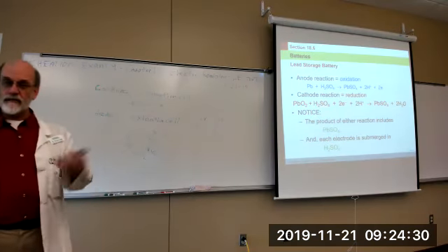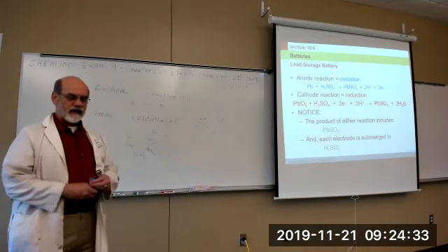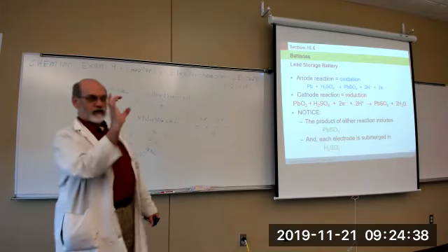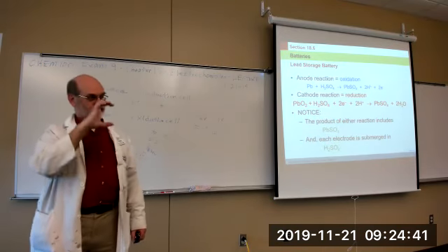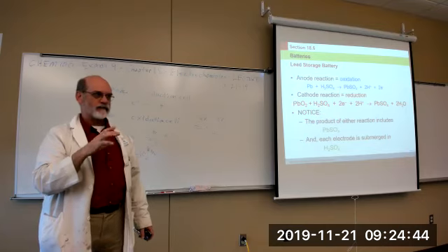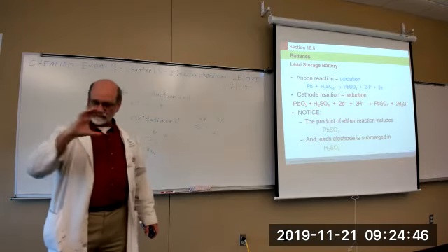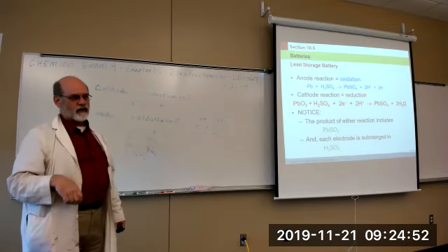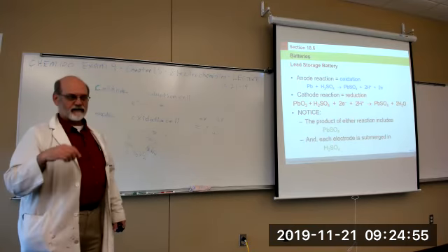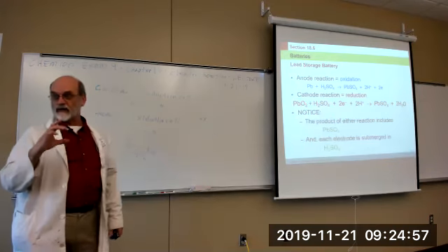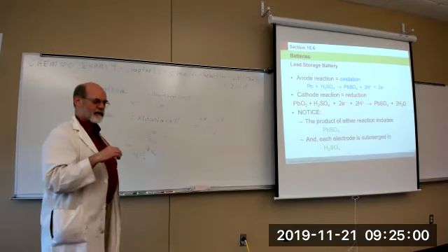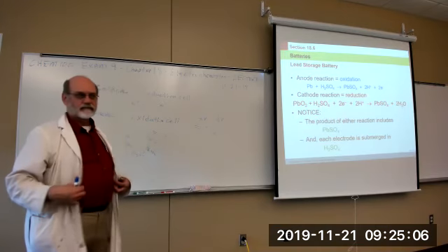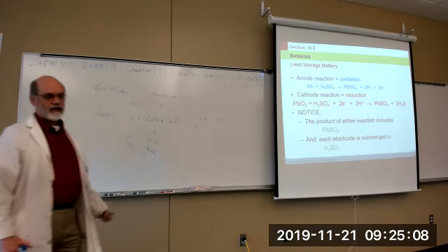It used to be you'd have to go to the service station periodically, and they'd stick a little tube down in your battery. They pull up some of the sulfuric acid, and it would read off whether it's strong enough. Right? It was using a hydrometer because the density would change. And if you needed some fluid in your battery, they just add distilled water to it, and then check it again to be sure that the acid concentration was at the right point. And if it wasn't, they could add sulfuric acid to your battery and build it back up. And usually that'd make your battery last longer.